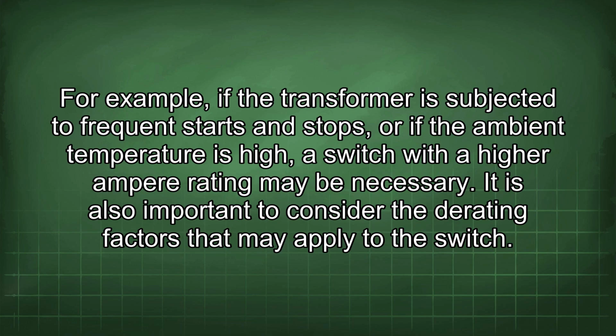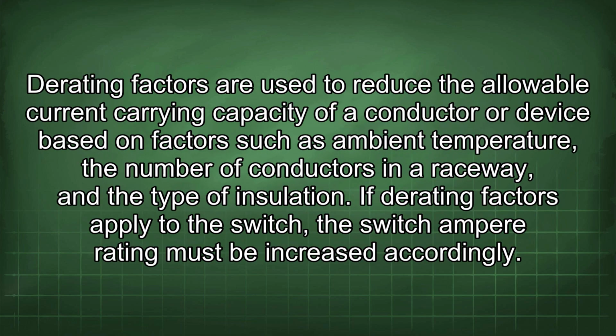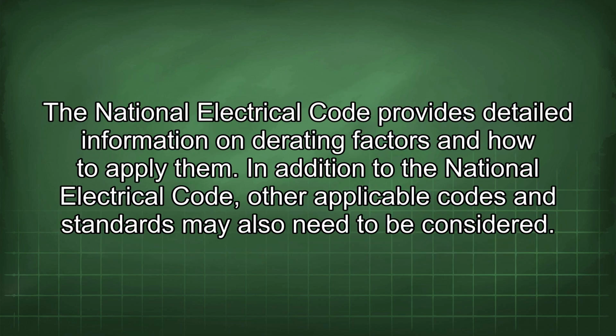It is also important to consider the derating factors that may apply to the switch. Derating factors are used to reduce the allowable current carrying capacity of a conductor or device based on factors such as ambient temperature, the number of conductors in a raceway, and the type of insulation. If derating factors apply, the switch ampere rating must be increased accordingly. The National Electrical Code provides detailed information on derating factors and how to apply them.